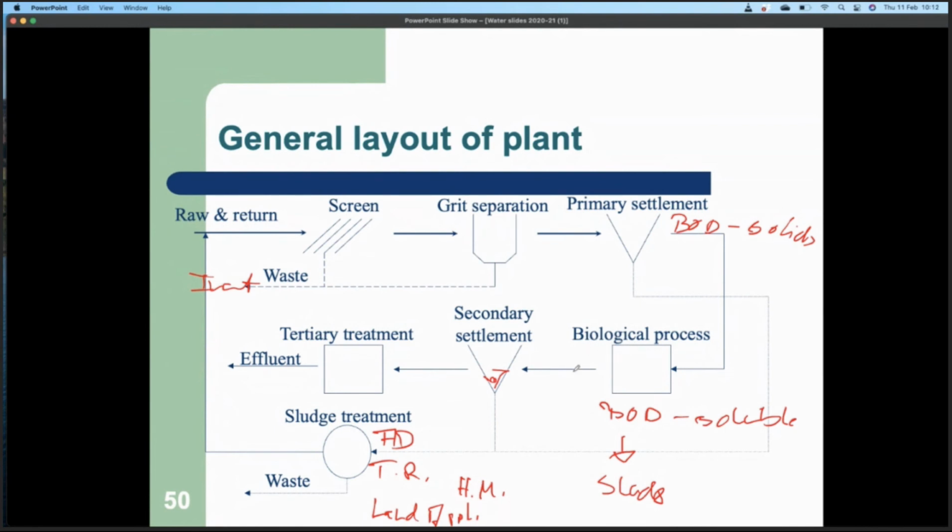You grow all these bacteria, you concentrate them, you put them through anaerobic treatment. That removes the organic fraction of the biomass and you're left with heavy metals. So sewage sludge is just quite rich in heavy metals naturally. There's nothing you can do about that. It's just the nature of the beast. So none of that treatment, pretty much no treatment whatsoever, is available to remove the heavy metals from sludge.